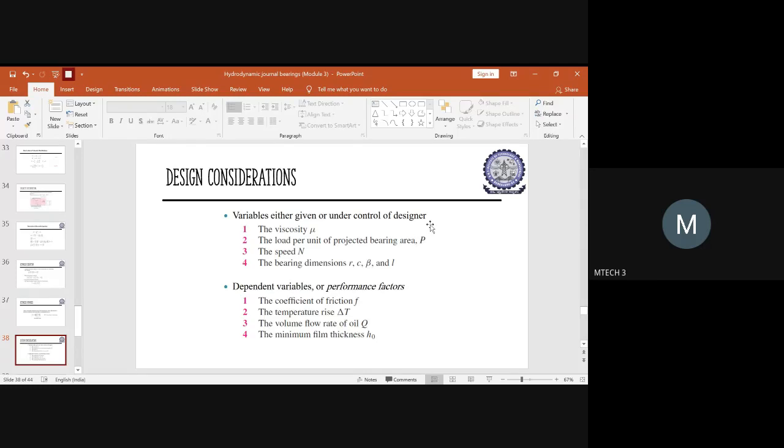So based on the application, you have to see which is the maximum load you can give for the bearing, so that there will be no large amount of wear or friction associated with it, because we use a lubricant of very thin film. And even the assumption is the same thing while deriving the Reynolds equation. So you should be careful about the load which will be subjected.